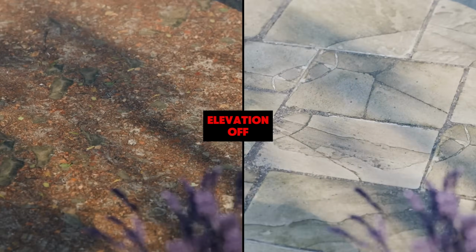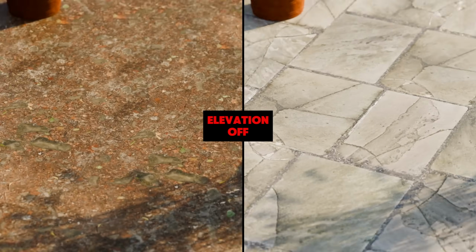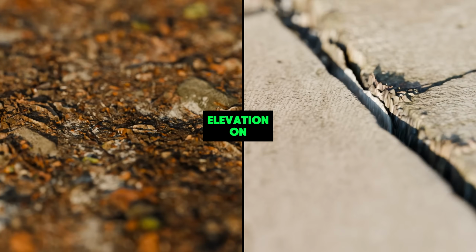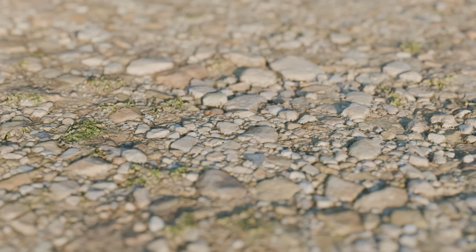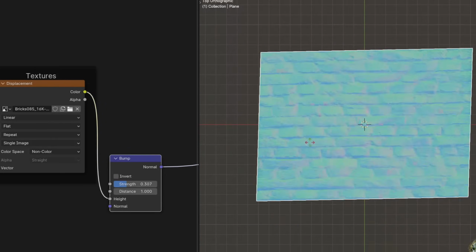The benefit of height maps is the amount of detail they offer, which appears perfect from every angle and under any lighting condition. The downside of using height maps for displacement is that the quality is limited by the amount of geometry your object has. Therefore, the more geometry you have, the more detailed the displacement will be, which also increases render time. A height map can also be converted into a bump, so it can be an alternative option for a normal map.